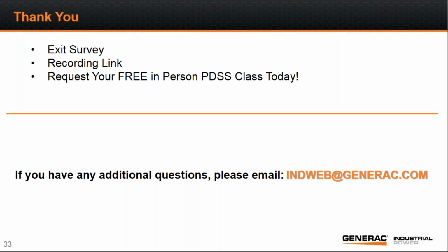Is there an oversizing rule of thumb for standard 6-pulse front-end VFDs? For standard 6-pulse front-end VFDs, 480-volt machines, you probably need about 2.5 times on the alternator. So if you have 100 kVA UPS or 100 kVA nonlinear load with 6-pulse unfiltered, you need about 250 kW on your alternator just to keep the voltage distortion in check.